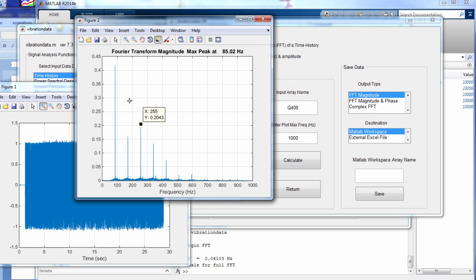There is an overall tendency for the amplitude of these harmonics to decrease as frequency goes on. And again, we have to take into account that the fuselage wall of that aircraft is probably much more efficient at attenuating the higher frequencies than the lower frequencies. So if we had an external microphone, that would have been interesting to do a comparison, and we could have calculated the transmission loss through the fuselage walls, but we're not going to go that far today because we only have the one set of data.